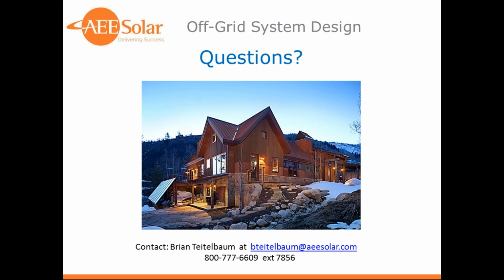But even now with something like Enphase inverters, it's certainly possible to use them in off-grid applications and AC coupled. Enphase hems and haws about whether they like that. It does wear on their internal switching mechanisms more than in a grid tie application, and I think there's potentially a problem with their lifespan at that point. But I certainly think that's a possibility.